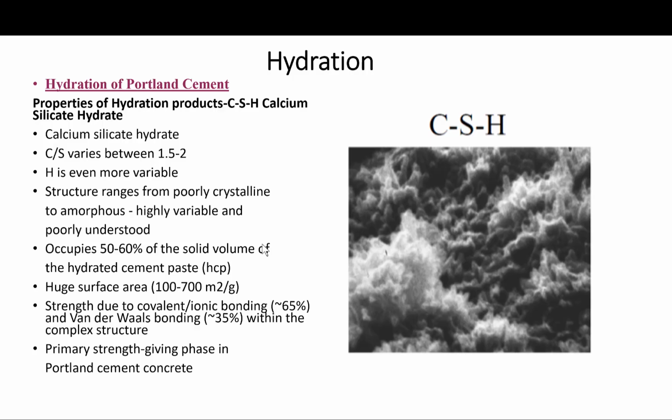So due to their colloidal dimensions and a tendency to cluster, the calcium silicate hydrate crystals could only be resolved with the advent of electron microscopy. In older literature, the material is often referred to as calcium silicate hydrate gel, and I have used this term often, if you noticed.